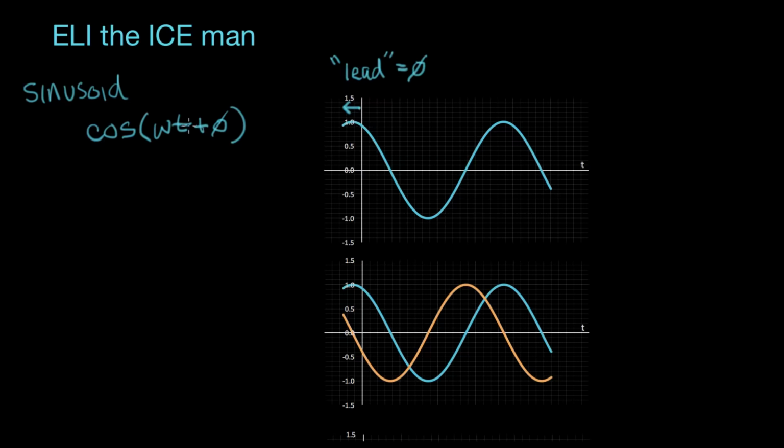So when these kinds of signals are input into our favorite components, we're going to get a relationship between the voltage and the current in those components, and it's related by the impedance. We've defined the idea of impedance as the ratio of voltage to current. We gave that the symbol Z. Now in this video, instead of using V as my variable for voltage, I'm going to use E. E is short for EMF, or electromotive force, and it's really commonly used almost as often as V for representing voltage.